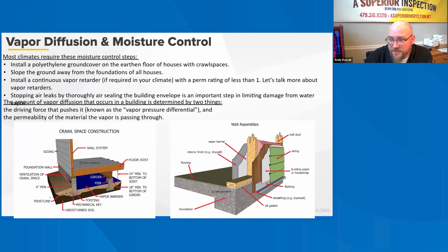Vapor diffusion retarders can help control moisture in basements, ceilings, crawl spaces, floors, slab-on-grade foundations, and walls. Effective moisture control in these areas and throughout a home must also include air sealing gaps in the structure, not just the use of vapor diffusion retarder. However, where and whether a vapor diffusion retarder is needed depends on the climate and the construction of the home.